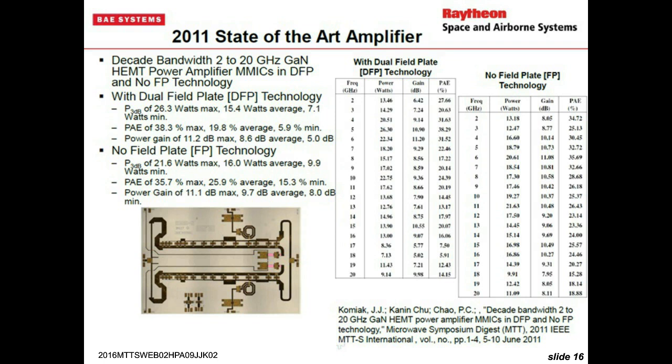The bias element is always the bandwidth limiting element on wideband amplifiers. And in this case, it's a spiral inductor that had to be wide enough in its conductors to handle the high currents and still give adequate inductance to meet the low frequency end and minimize the parasitics, shunt capacitance and interwinding capacitance, so it still worked adequately at the high frequency end.